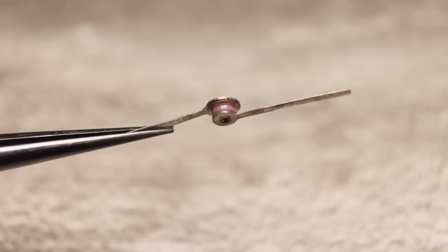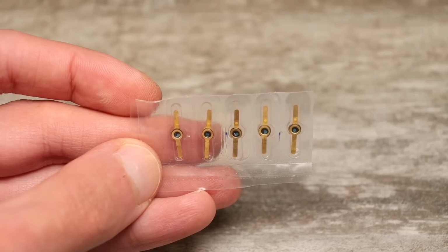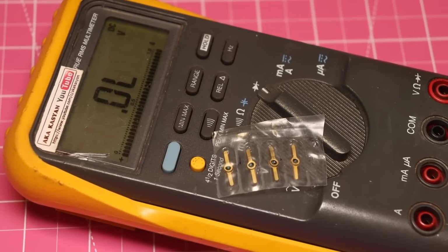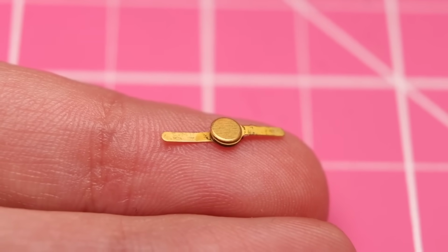A tunnel diode is a rather finicky thing. It's sensitive to high voltage exceeding the tunnel current and static electricity. Even a routine check with a multimeter can kill it, so you have to handle it with the utmost care.